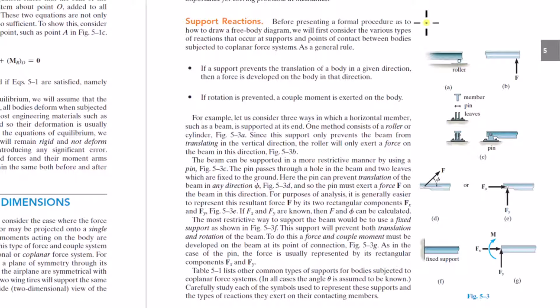So a crane lifting something, the force from what it's lifting is part of how it operates. That's an external force. A cross beam in a building, the force from the people, the furniture, the weight on the beam, that's an external force. If it's not an external force, then it's going to be a support, which is called a reaction force.